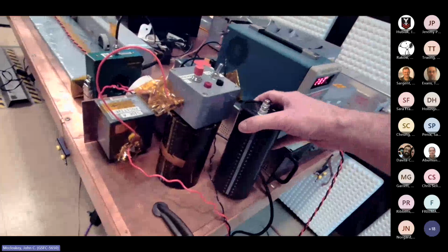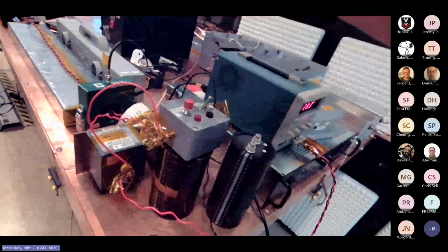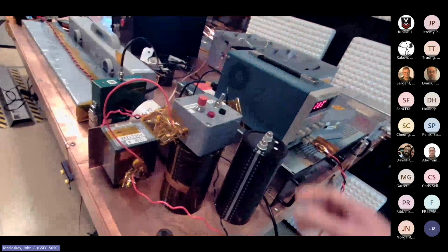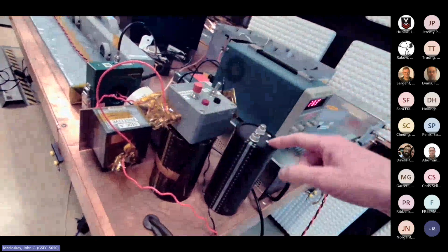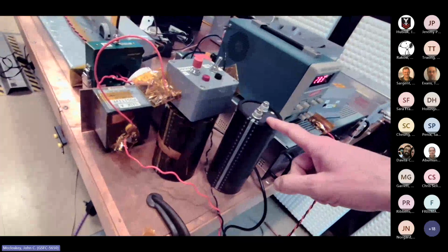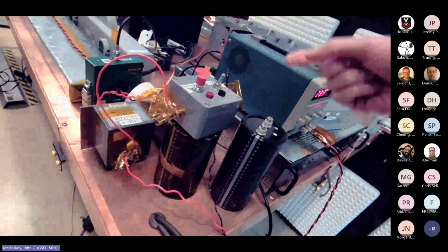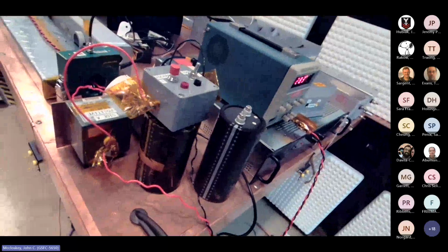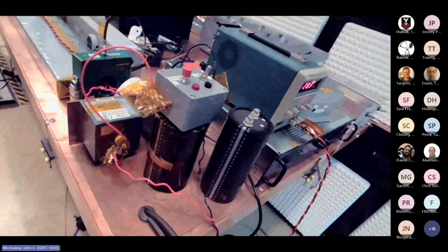But if it's a DC system, we'll put this 10,000 microfarad capacitor across the pair of 10 microfarad caps. So you lower that source impedance down to 30 hertz, which is the lower end of the frequency range that we test to. If you do the math, the 1 over j omega C, the 10 microfarad caps are about an ohm at about 20 kilohertz.